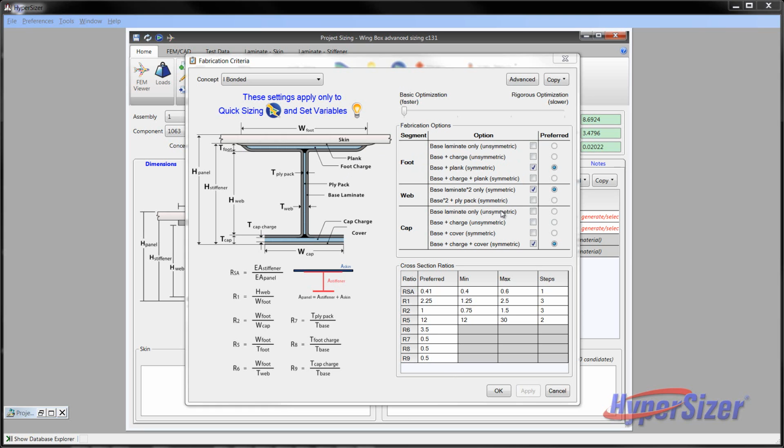These options relate to how your company will fabricate the stiffener. Since it involves tooling which is directly related to manufacturing cost, the decision of which option to use is subject to a specific manufacturing approach. If your company has one particular approach, then put a single check in a box. However, the software will allow you to put a check into as many boxes as you would like to be considered.